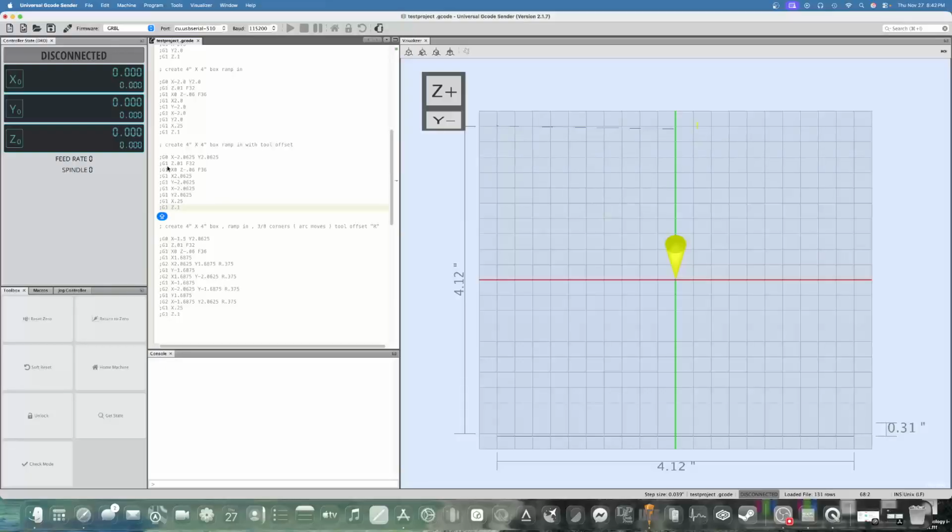Even then, if I was writing G-code, I still wouldn't use it simply because I'm just used to IJK. But IJK fully defines how you want that radius. And unlike R, you can't use R to do a full circle, where with IJK you can. The start and end points are the same, and you'd simply set it with I or J to make the circle on the side you want.